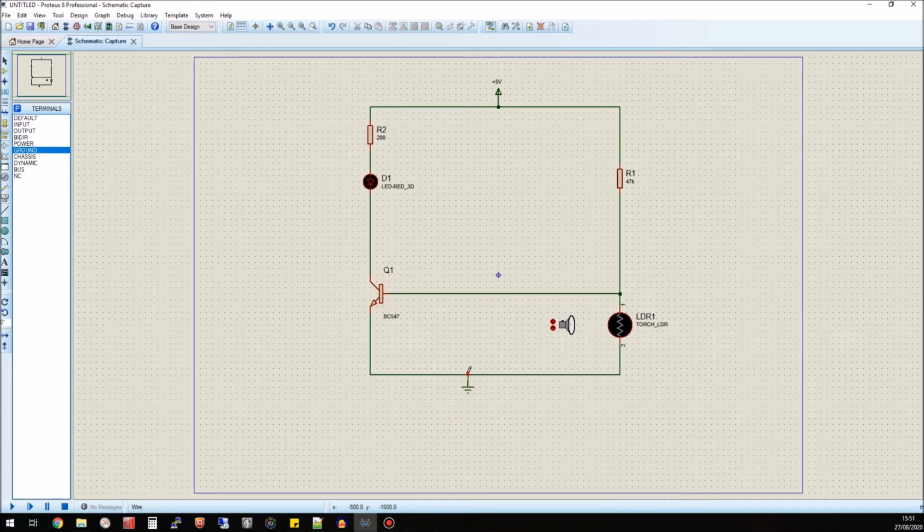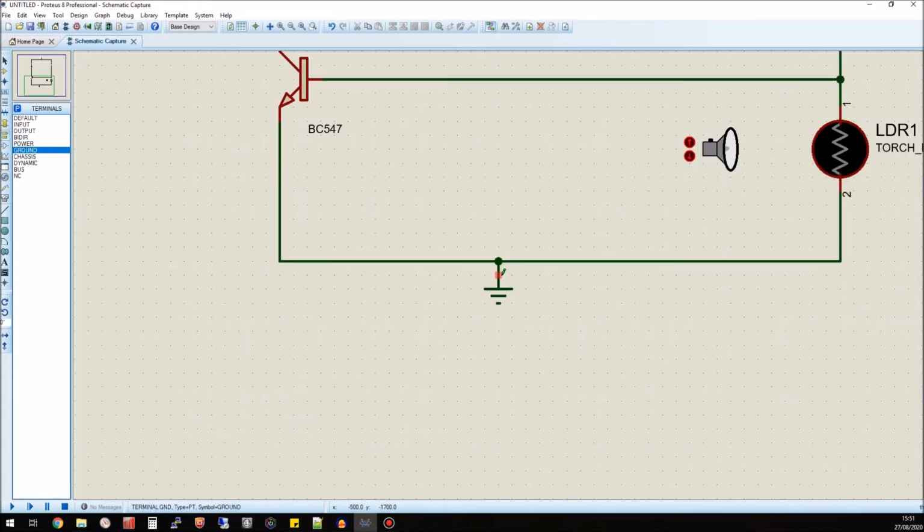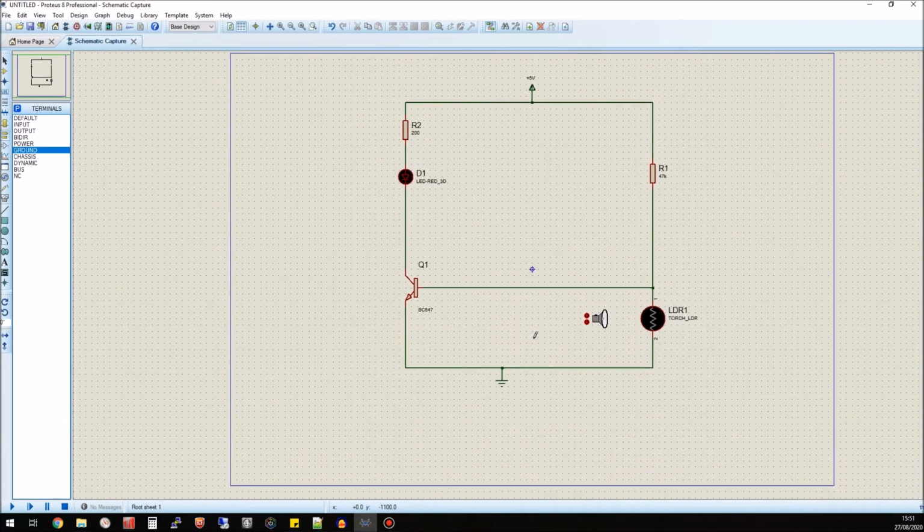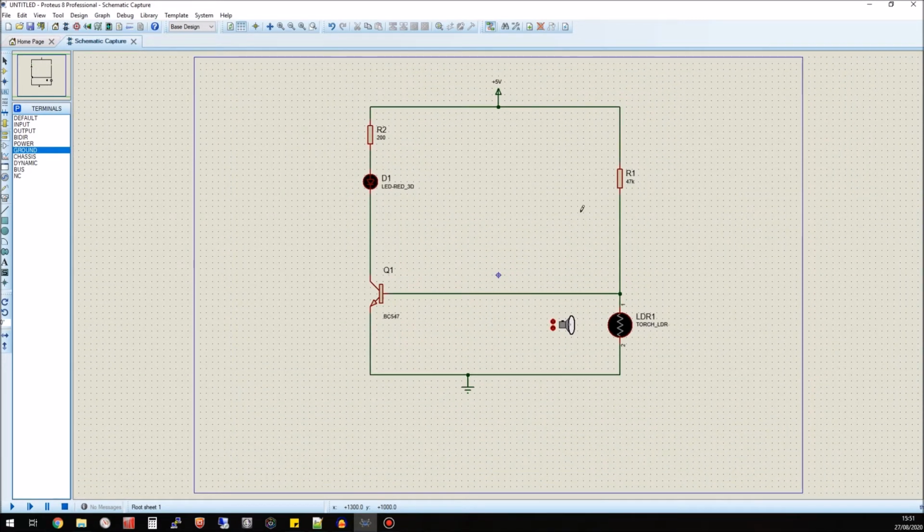This is necessary for simulation, as the virtual oscilloscopes and meters automatically use the ground rail as a reference. If there is no ground specified, they will not produce a sensible reading, or may even throw an error. Next, we can check the circuit's function using the simulator.